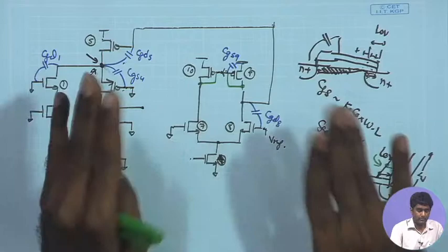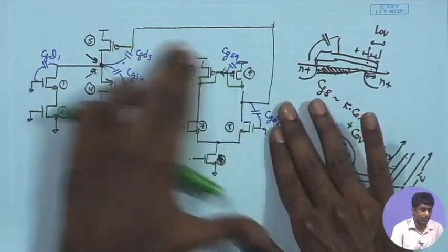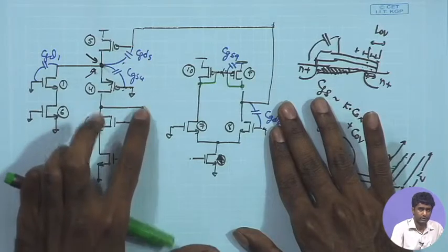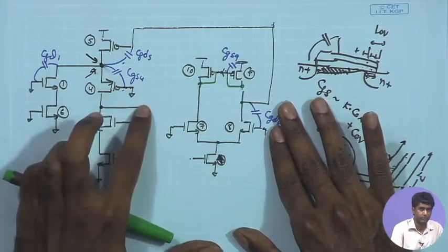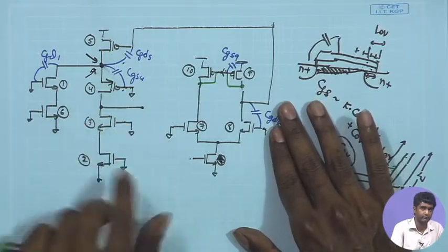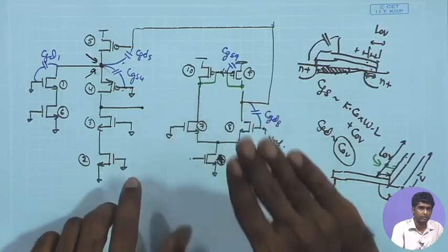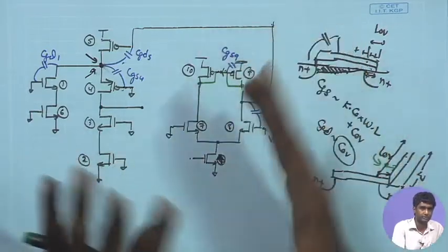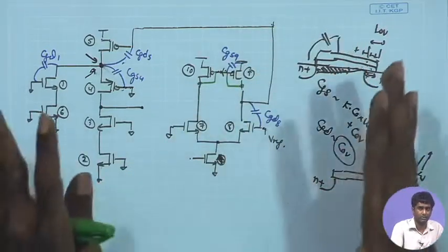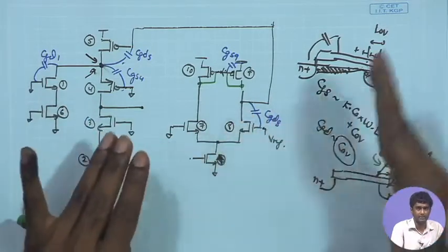We will see that if you want to compensate the common mode loop, right now we are constrained with the single loop, and the same CC over here or same CL over here is good enough for compensating both. But in some applications you may have to keep the bandwidth of the common mode feedback loop much lower than the differential. In that case more complications arise, and we can look into schemes where these two can be compensated separately.